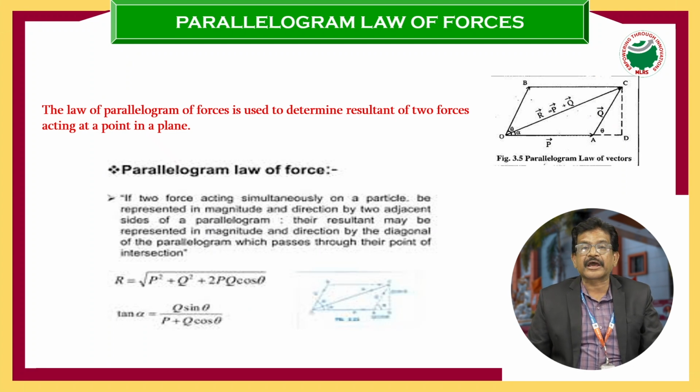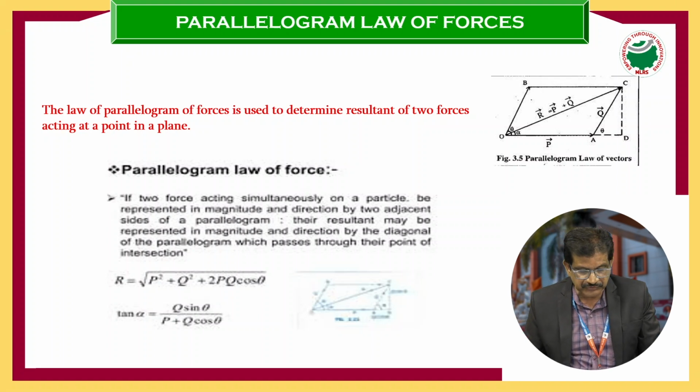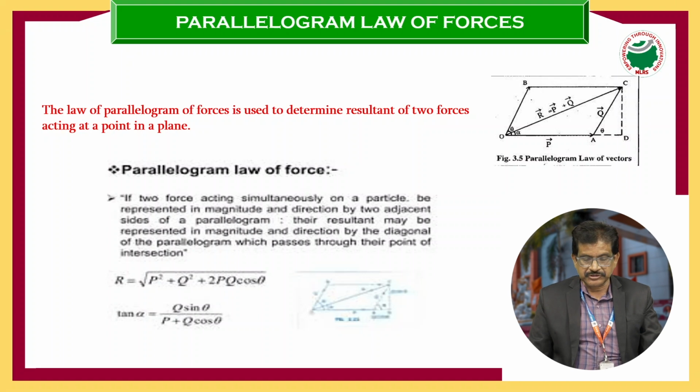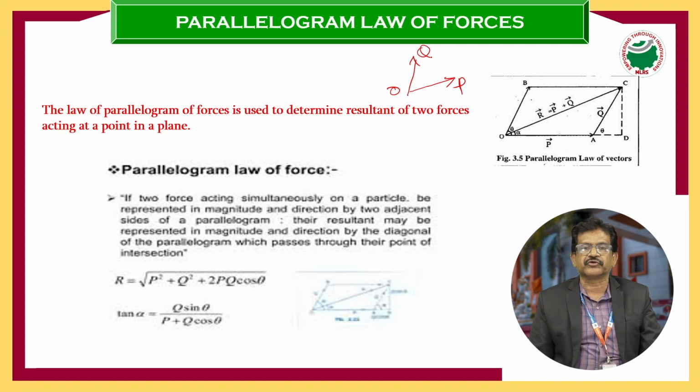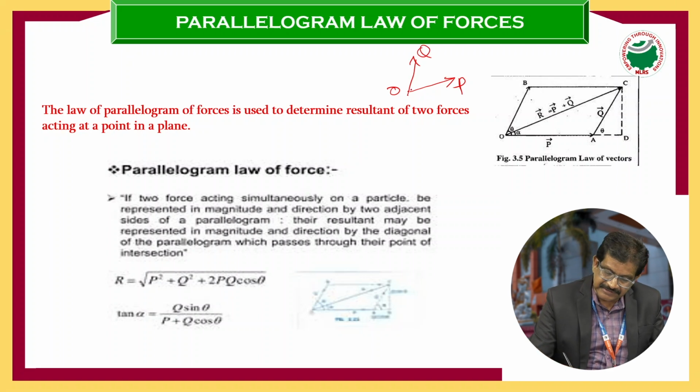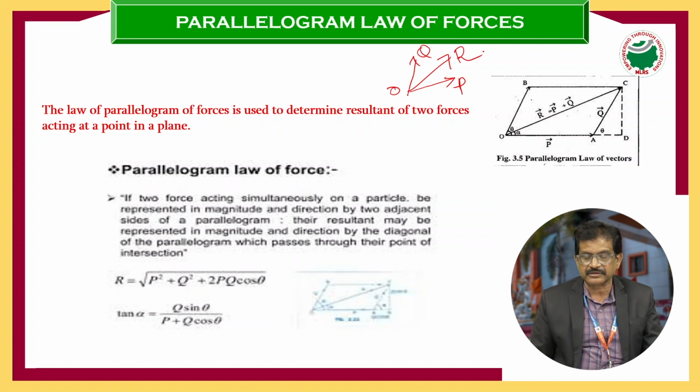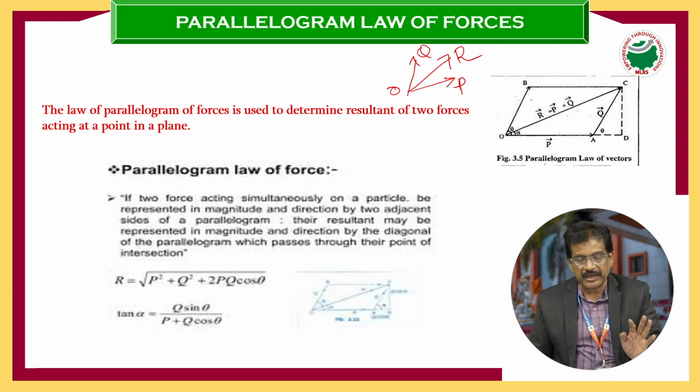Next one, parallelogram law of force. What is the use of the parallelogram law of force? It is used to determine the resultant of two forces. Take this example. Here I am applying one force P. Again here I am applying another force Q. So now the resultant is R. This R is given by the parallelogram law of force.